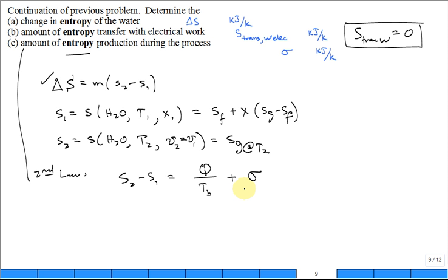That's sigma. Entropy generation. True. Was there any other? It's a closed system. There's no mass transfer. So in this system, why is this term equal to 0? It was a well-insulated tank. And so if I want to calculate the entropy production, it's equal to the same numeric value as the answer for part A. So sigma is equal to that. Boom, boom, boom. Got it?